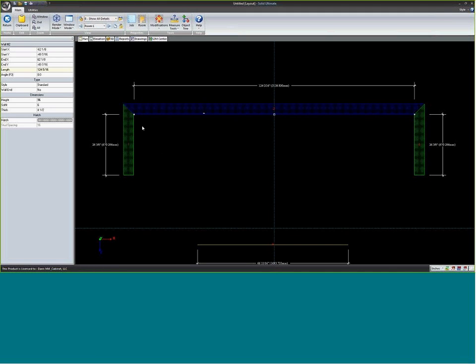Other things that are important on an individual wall. Notice over here I've got a wall height, so I can customize wall by wall what the height is. I've also got a soffit height, and this is a little misleading to some people. A soffit, most people think of the ductwork or something being covered by sheetrock or plaster hanging down from the ceiling. In this case, that's not what it is.